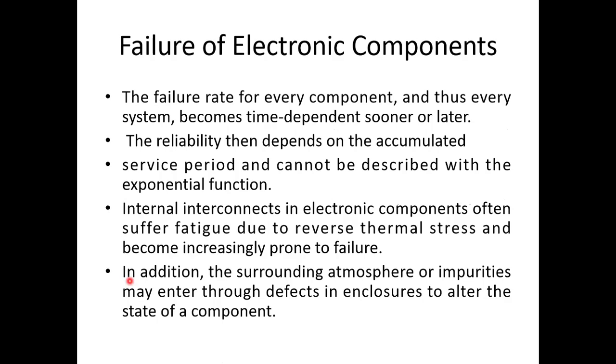So the failure rate for every component and every system becomes time dependent sooner or later. The reliability then depends on the accumulated service period and cannot be described with the exponential function. Exponential distribution is very important, but we cannot predict.